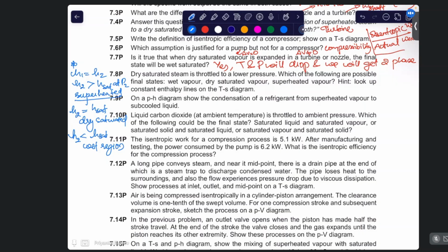So the final mixture typically could be vapor plus solid if final temperature is below the sublimation line. In some cases, we could also have a bit of liquid if we are above the triple point. Hence, it depends on initial condition and how the constant enthalpy line crosses the phase boundary. Often, we will be getting the solid plus vapor mix, or dry ice plus gas.